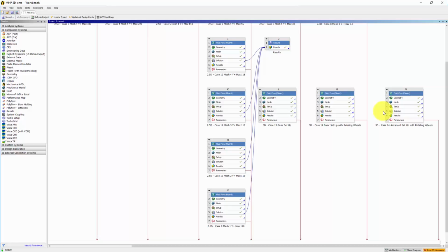Like the 2.5D simulations, let's set the geometry up, create an auto-generated mesh, and set up Fluent. This will allow any issues that may arise, like missing faces or incorrect directional vectors, to be quickly fixed. Now let's duplicate this simulation and check the geometry out.